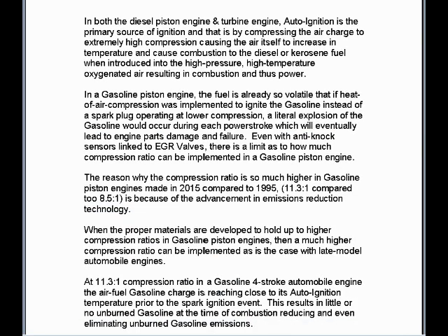In both the diesel piston engine and turbine engine, auto-ignition is the primary source of ignition, and that is caused by compressing the air charge to extremely high compressions, causing the air itself to increase in temperature and cause combustion to the diesel or kerosene fuel when introduced into the high pressure, high temperature oxygenated air, resulting in combustion and thus power.